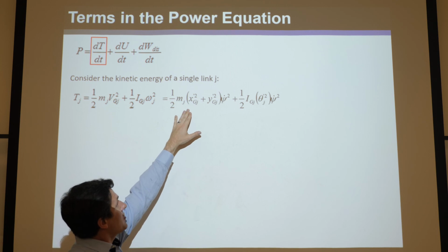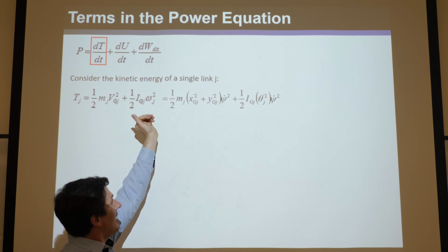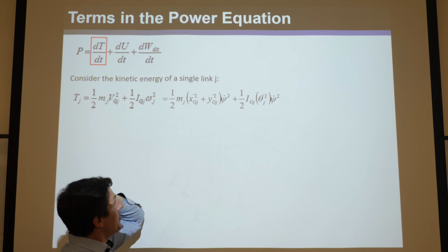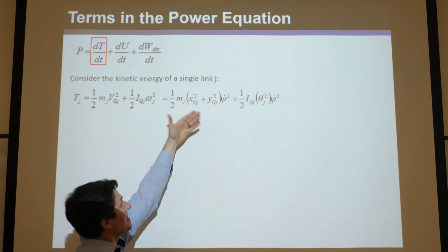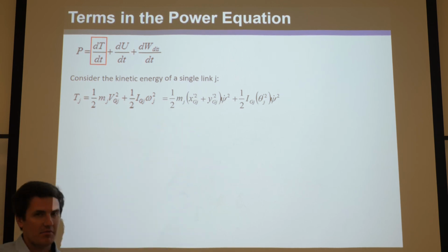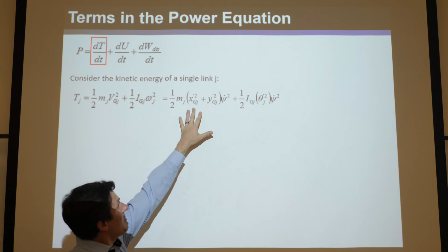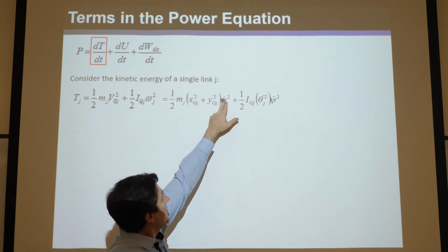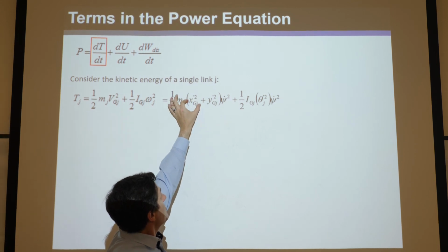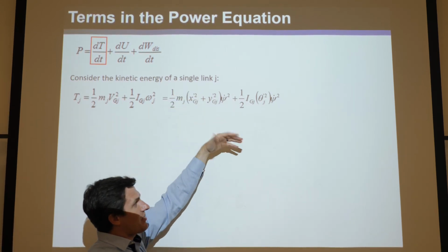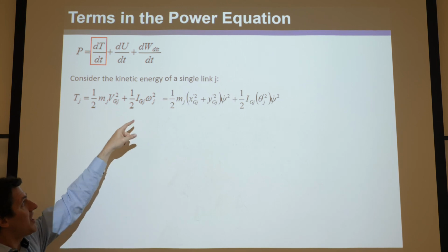Remember, if you take the first order kinematic coefficient, the x component, and you times it by phi dot, with respect to derivative with respect to time, you get basically the velocity of that x component at the point g. Okay, and same thing if you do the same thing with the y component, and basically if you do this, pull that in and notice that's squared, you could imagine each component squared adding together. That'll be the square of the total velocity at the point.